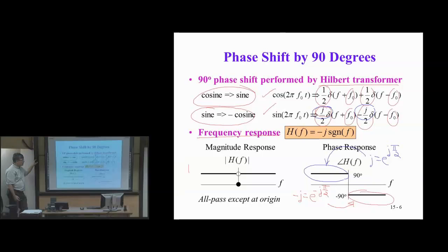Now, what's your guess at the impulse response here in terms of symmetry? Any symmetry you think is here? Any symmetry in the phase? Yeah. What's the symmetry in the phase? Odd symmetry? Correct. I'll have odd symmetry in the impulse response, about the center of the impulse response. That's right. About the midpoint, if you will. Right. Okay.